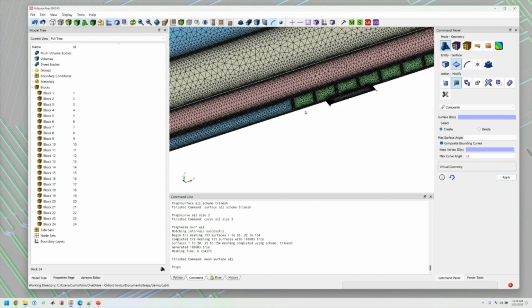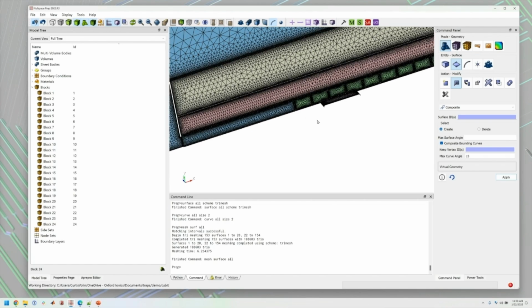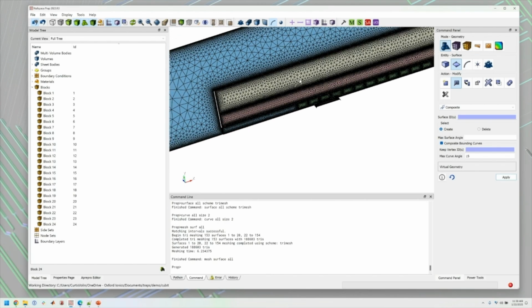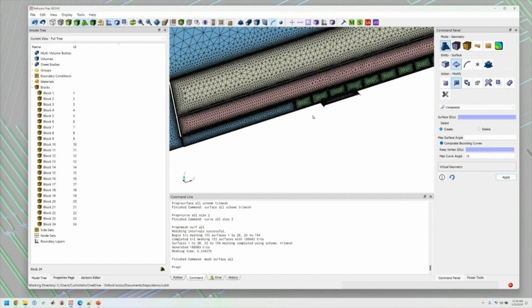Then in order to get the potential of just, say, the electrodes in the plus y plane, we take the sum of those 2 models. And in order to get the potential in the minus y plane on those electrodes, we take the difference of those two models. And then we have a complete set of data. The advantage of doing that is primarily in runtime. The runtime of the model is generally proportional to something like the square of the number of triangles.